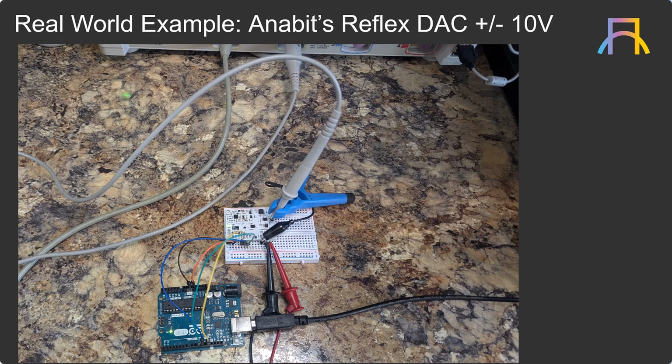Right, so here's the setup I'm going to show you an example measurement from. So you can see the Reflex DAC, and then we have an oscilloscope probe connected to the output of the buffer amp. So we're getting that unipolar DAC signal that's inverted. We're going to measure that. And then you can see 2 clips, a black and red clip. That's measuring the output of the summing amp, or the output of the whole circuit, right? So that's where we should see that plus to -10 volt range.